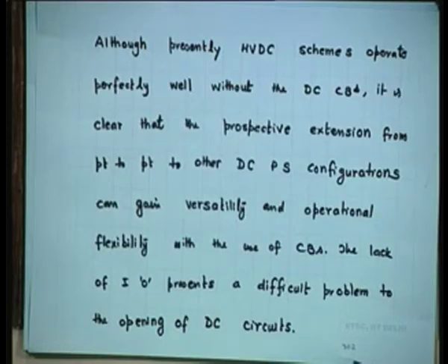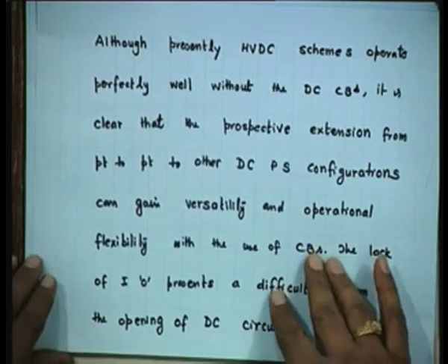The lack of current zero presents a difficult problem to the opening of DC circuits. This I already told you, this is the real problem, because we do not have a natural zero occurring like in AC.